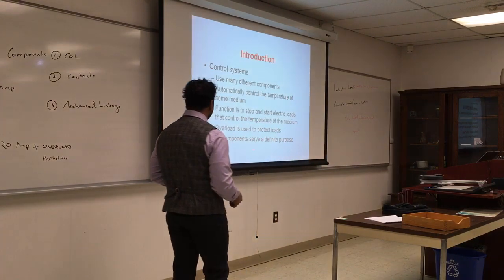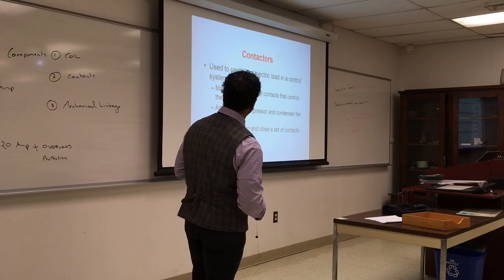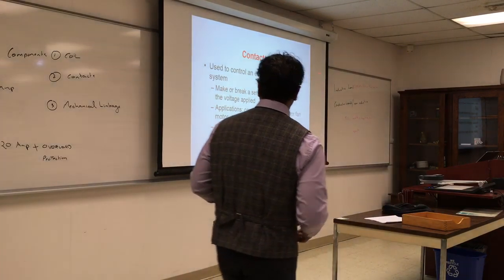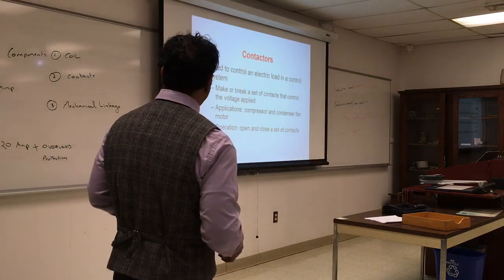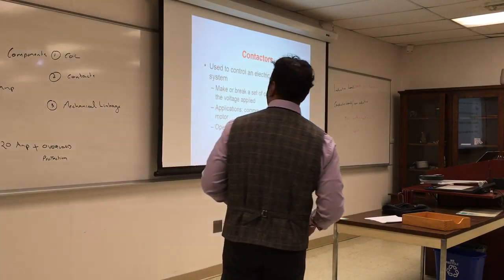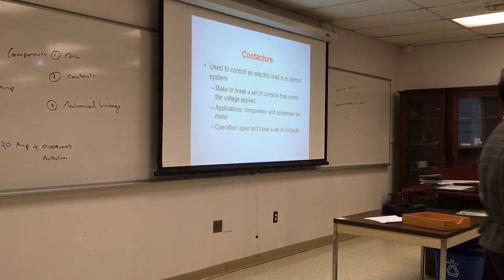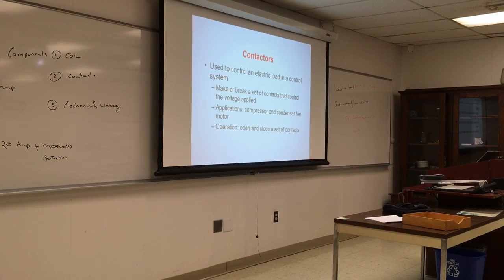Overload purposes. Contactors. So these are the contact and the contactors. For the contact, it's a relay that will turn on a low voltage control into a high voltage load connection. So for the AC, you turn on the compressor, using the thermostat as the low voltage circuit, 24 volts. It will close a contact, and the contact will make a circuit that is 220.